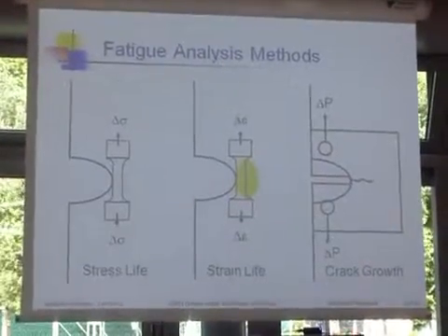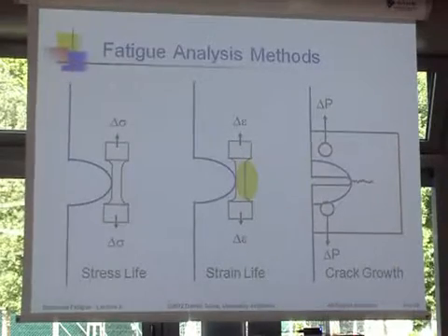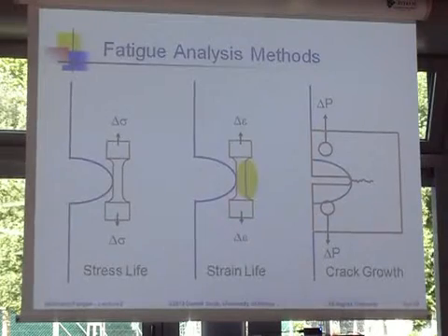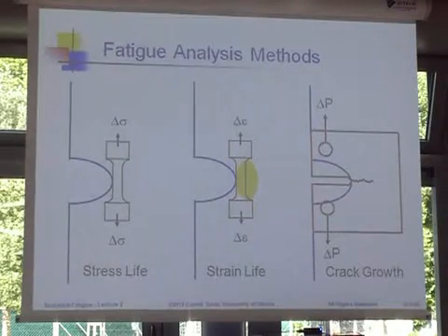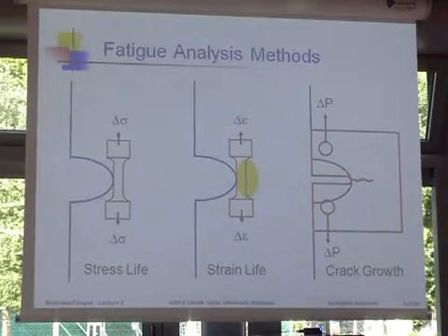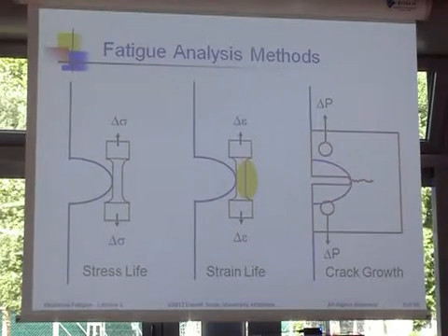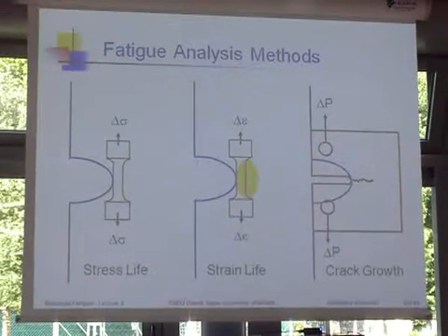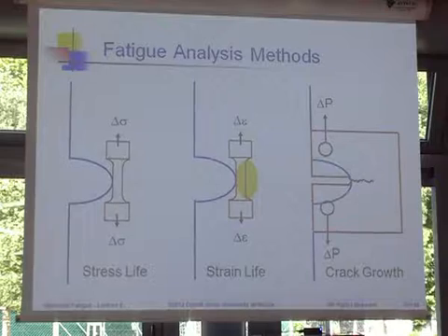And I have my little cartoon, so think about I have this little cutout geometry that we talked about before, and I look at the different ways of doing things in the different models. You know, in stress life, we just assume everything is elastic. And in strain life, we say, fine, we have to somehow deal with the plastic fields in front of the cracks and how cracks grow there.